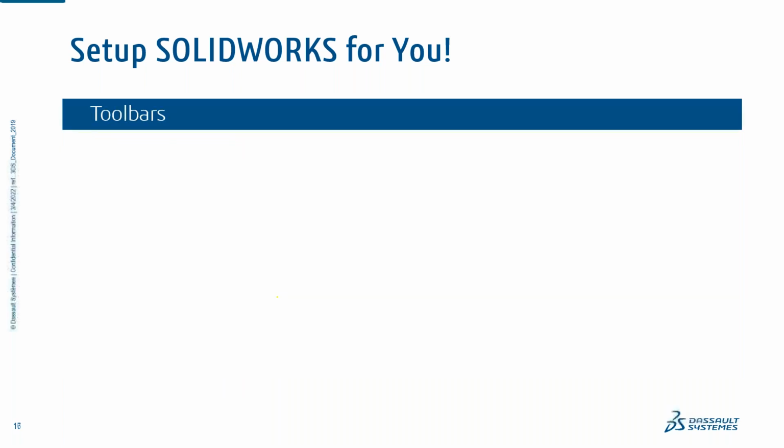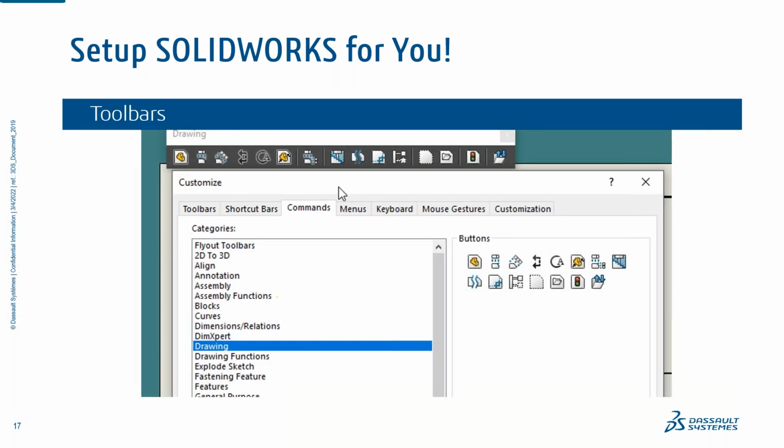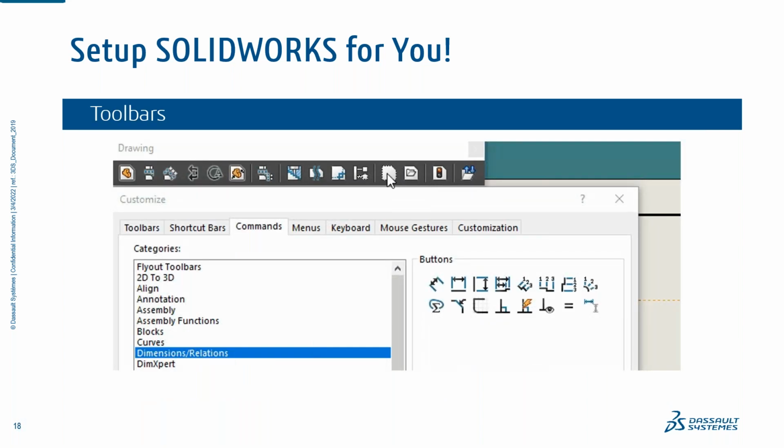And let's see. So you can even customize them individually. So here in this drawing, I don't need some of this other stuff. I can customize them as needed. So I don't need this view, and all you've got to do is grab and drag it out, just like the command manager. I don't need it, so we're just going to drag it out.